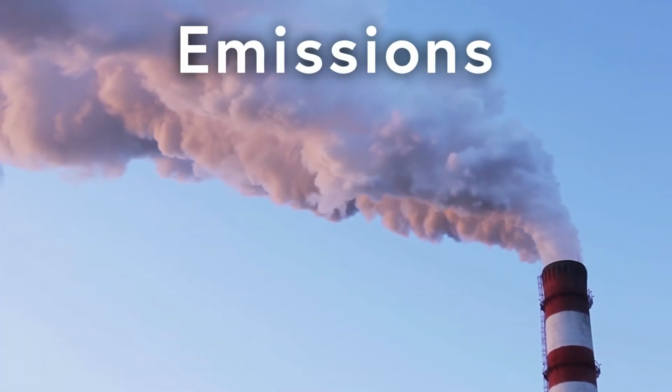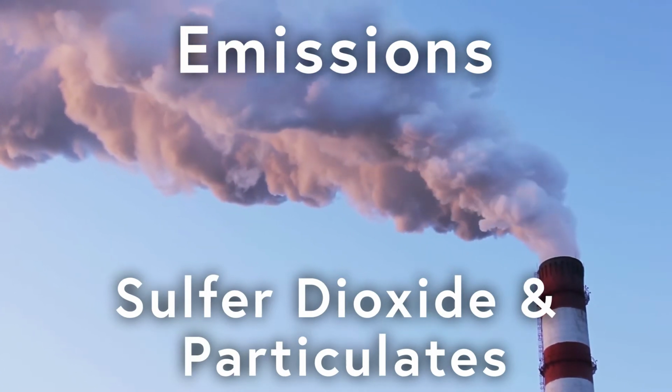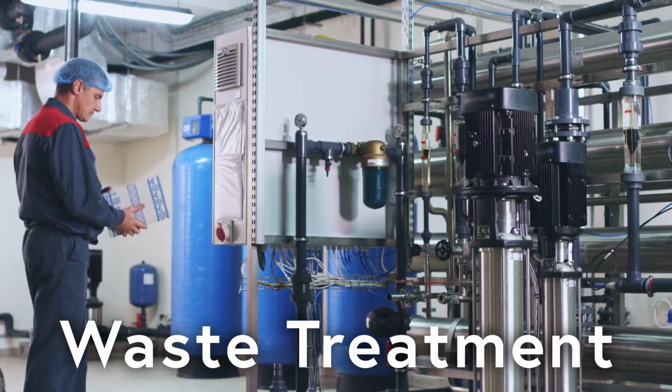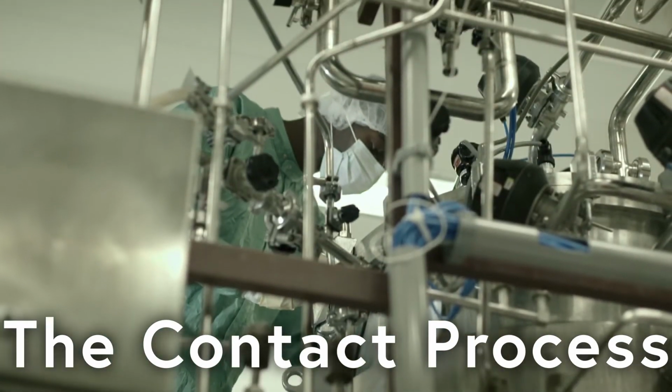The processing of copper produces air emissions such as sulfur dioxide and particulates containing iron, copper oxides, and sulfates. Treatment methods for this waste include capturing particulates by using emission control equipment and turning sulfur dioxide into sulfuric acid through something called the contact process.